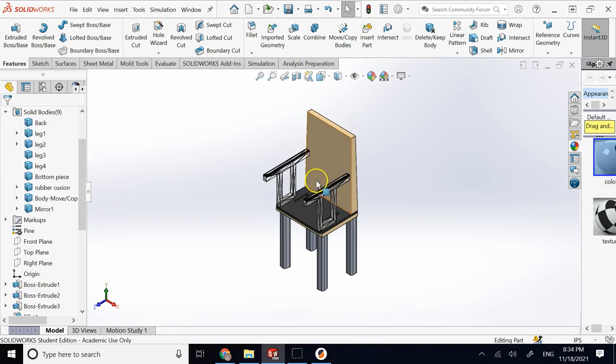Again, in here, the connection is static. The parts are not going to move with respect to each other, whether we combine them or not. It's not like assembly where you apply joints, you apply constraints, and the parts can move with respect to each other if you want. The positioning here is not as accurate as assembly. And if you want to do that, you have to do a bunch of measurements. So if you really care about checking interference and tolerances and everything, you better use assembly instead of here.